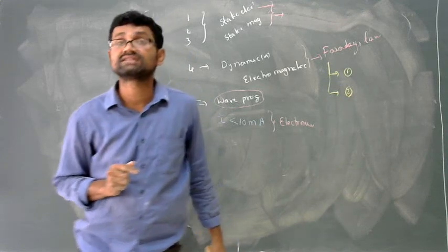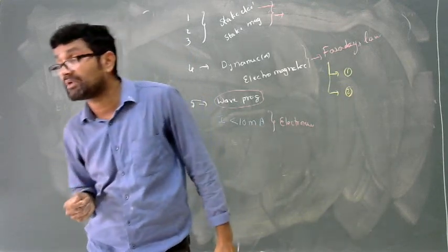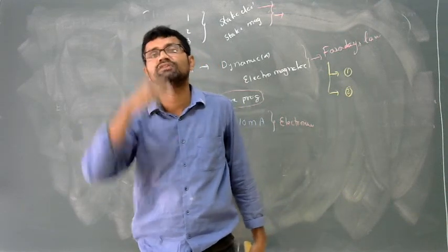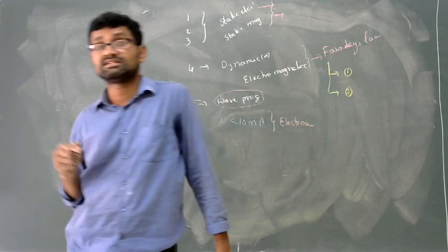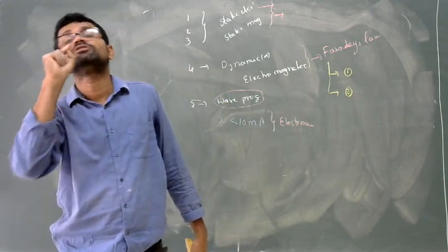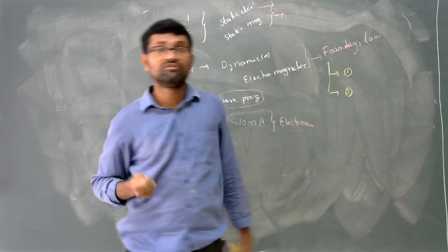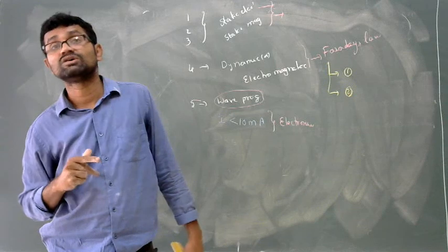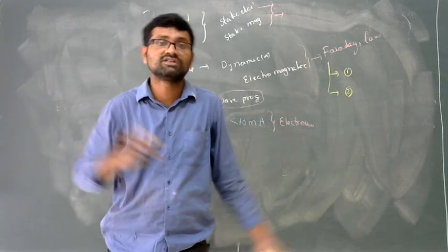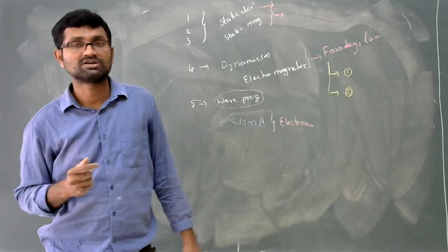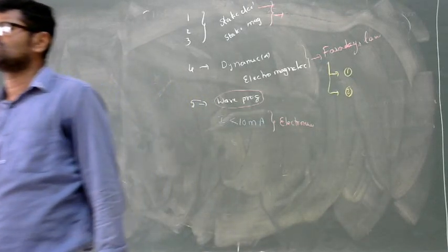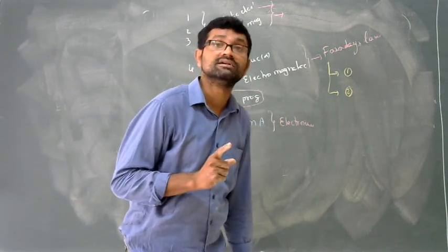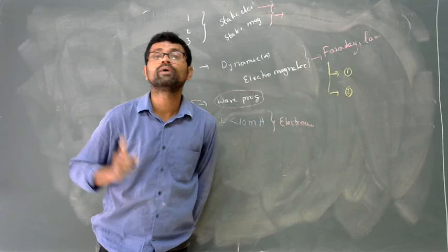Based on the direction of current, to make current flow we have to provide a closed path to the conductors. If you provide a closed path with a resistor, and currents enter that resistor, the entering terminal is the positive terminal and the leaving terminal is the negative terminal. So by knowing the current directions, we represent the voltage source polarity. Otherwise, it is impossible to represent which terminal is positive and which is negative without knowing the currents. That's why, to flow current, we have to provide a closed path.